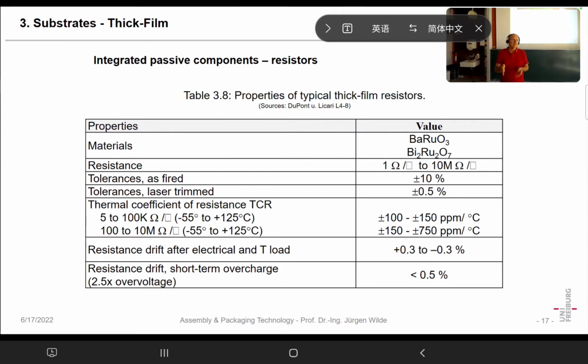Metals, what's the resistance over temperature? Yeah, the resistance will increase with temperature in a metal. So also in a highly doped silicon, resistance will increase with temperature because the mobility of the carriers is degraded. Yeah, so that's a metal.